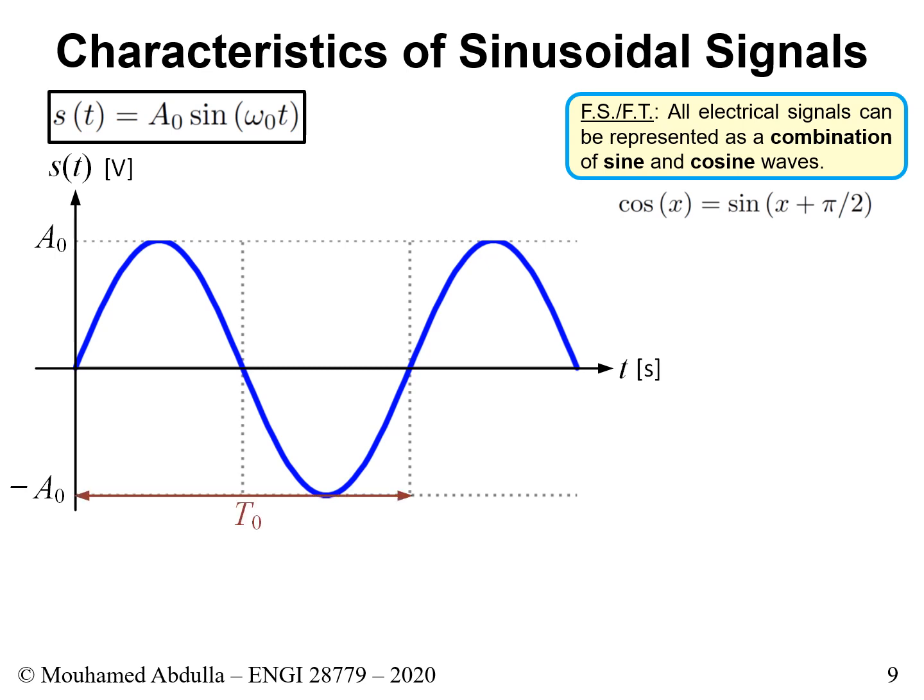What else can we identify? Well, the other thing that we could right away get from the picture of a signal, and of course you could do all this with your oscilloscope, is you could put a cursor and then you could find the period. The period is right away the cycle. So this is one cycle, and then the pattern repeats itself. So therefore, this thing here gives us the period. This is the period of the signal.